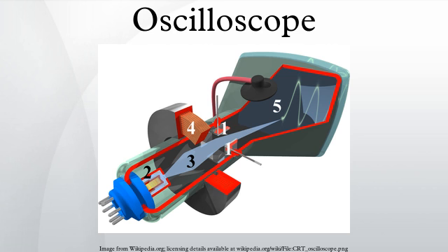Handheld oscilloscopes. Handheld oscilloscopes are useful for many test and field service applications. Today, a handheld oscilloscope is usually a digital sampling oscilloscope, using a liquid crystal display. Many handheld and bench oscilloscopes have the ground reference voltage common to all input channels. If more than one measurement channel is used at the same time, all the input signals must have the same voltage reference, and the shared default reference is the earth. If there is no differential preamplifier or external signal isolator, this traditional desktop oscilloscope is not suitable for floating measurements.